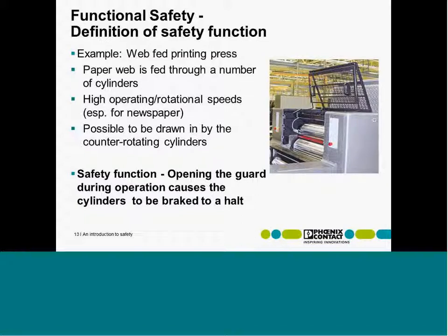A control element might be, for example, a classical PLC, a programmable logic controller, as an automation system, but it might also be electromechanical things like a relay. Hydraulic and pneumatic valves are also part of the safety loop. Often an emergency stop device is part of this functional safety aspect. So all things related to the control circuits, whether hardware or programmable software, are covered and seen in this functional safety.